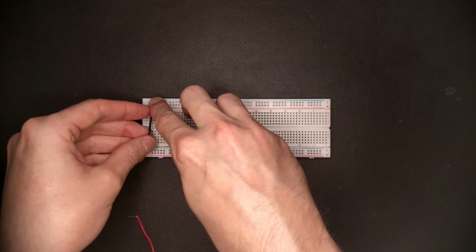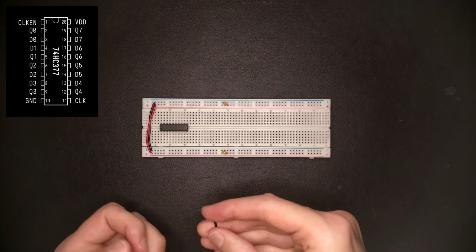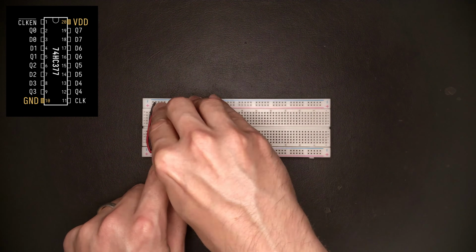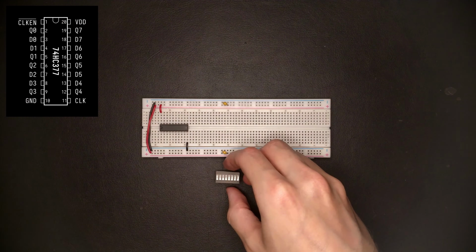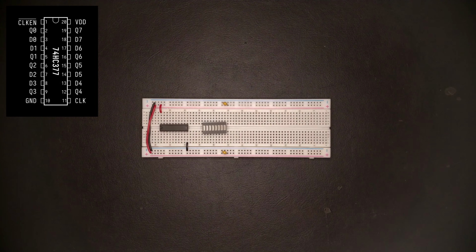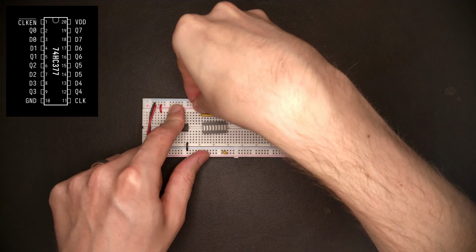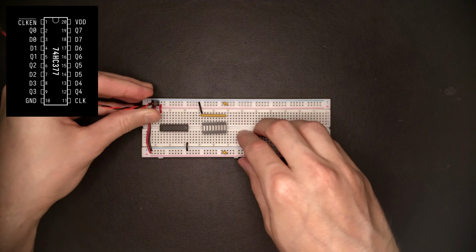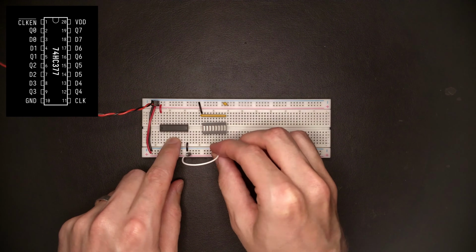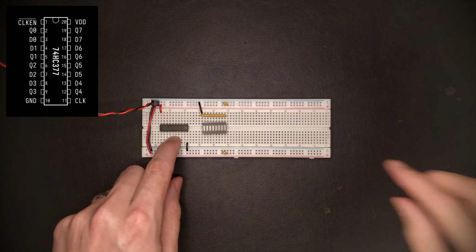Let me also connect the power rails of the breadboard. Let me hook up power and ground of the register. So I think we're going to add one of these bar graph LEDs to show what's currently inside the register. We'll need a resistor array. And a quick check to see if the LEDs are working properly. That appears to be working.